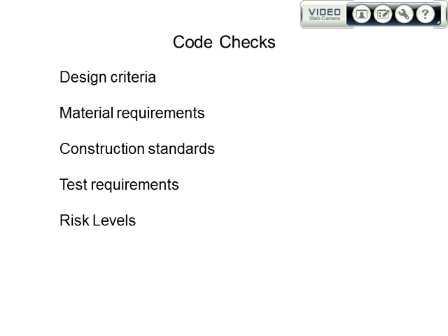So, for example, design criteria, the key thing with design is going to be the design factor. And the design factor depends on how you've set the pressure. The pipeline already exists, so you've got the wall thickness, and you know the material. Does the material comply with both codes?